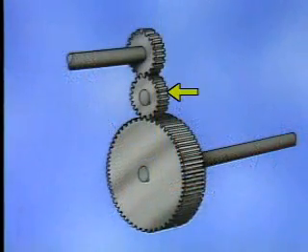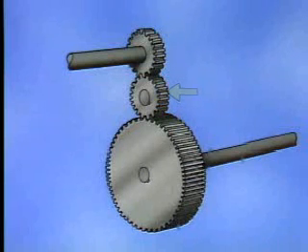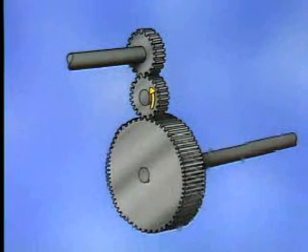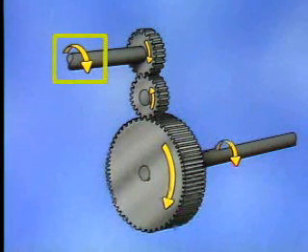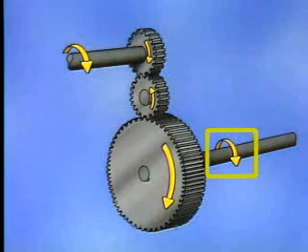The idler gear is just another spur gear that is mounted between the original gear and pinion. The idler gear spins freely and transmits the power developed on the pinion to the gear. This way, the input shaft and the output shaft will turn in the same direction.